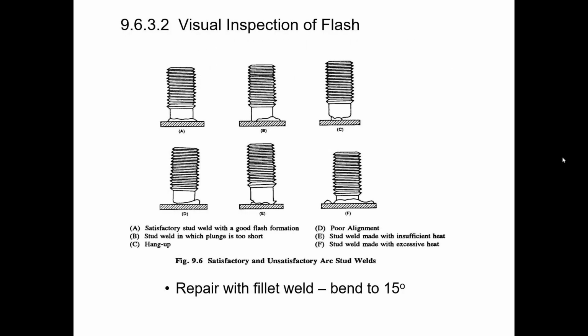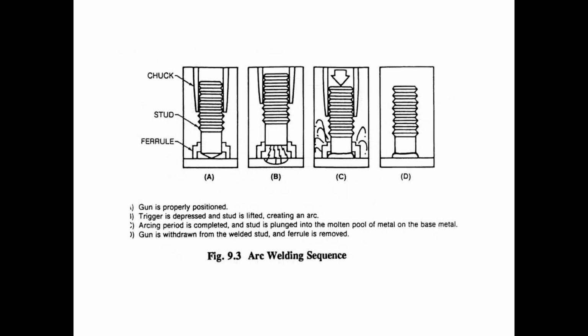So the purpose of that little point is that the stud gun has a little shoe on it, and that shoe is what helps you orient the gun in a theoretically perfectly upright position. It's a wider, flat surface. If the tip of the stud were flat, it would be harder. It would be maybe deceiving to think that, okay, it feels like I've got it vertical. The point is just a single point of contact, but it also facilitates that arc reaction.